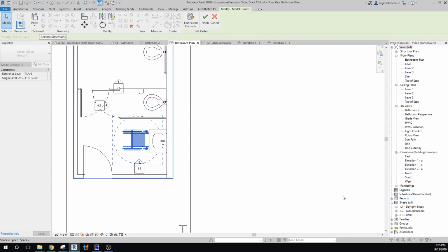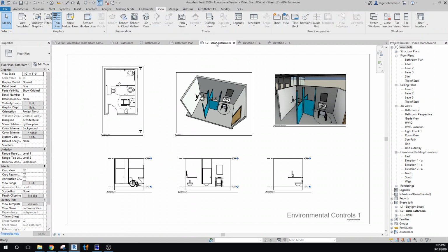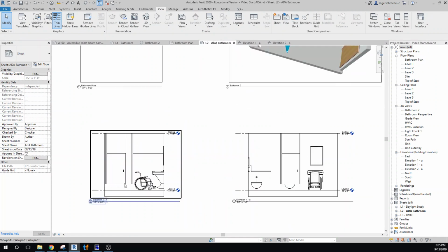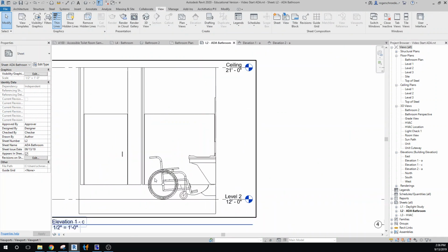Putting it right in front of the sink, because what I want to do is go to our bathroom, and I want you to be able to see this elevation, the relationship between the sink, this idea of a toe space. So you'll notice that down here, the depth of the stalls and the bottom of the sink are all accommodating this idea of toe space, space that you can get the chair up close to the front without your feet hitting the wall surface, which is really important if you're in a sitting position and trying to manipulate surfaces. So now it's possible to get up close.